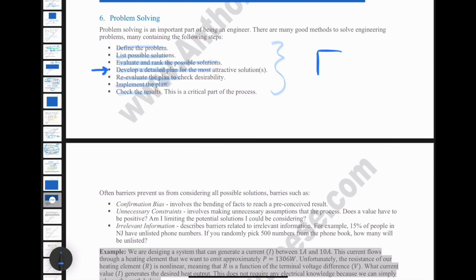If I give you a circuit, okay, with independent sources and constant resistances, and I tell you I need to know what the total power consumption is for all the resistances, you don't need to rank possible solutions there. I mean, it's pretty straightforward. You can use something like a nodal analysis to solve, and then you just have to simply calculate the power consumed along all the different lines.